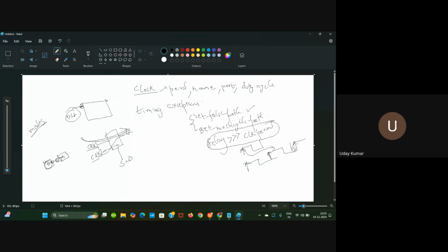So what will the top-level person do? He will go for flat STA runs and calculate the delay here, and he will update our SDCs, and we need to set the delays as he has given us. That particular process is called timing budgeting.